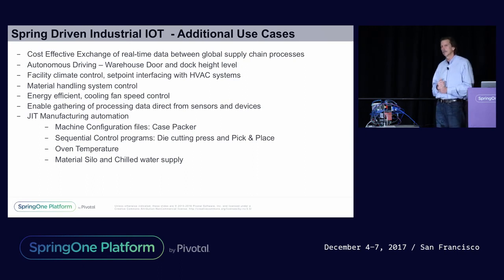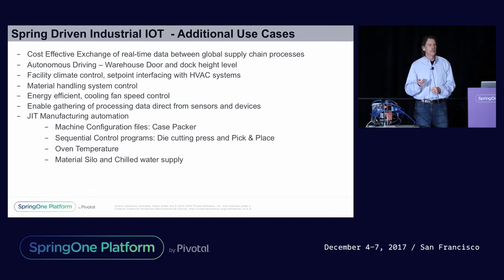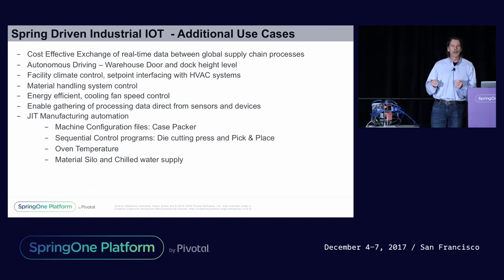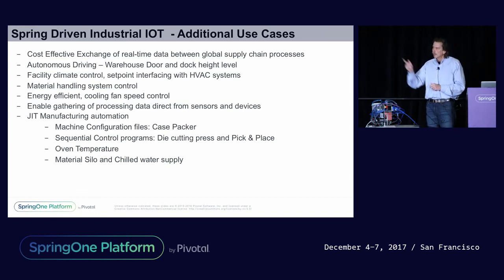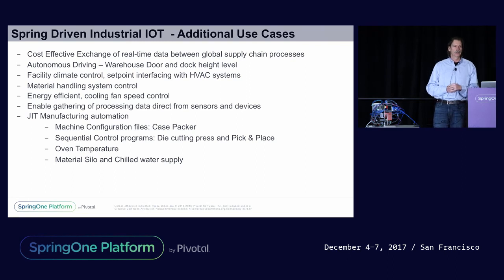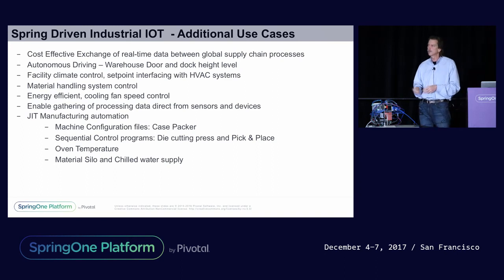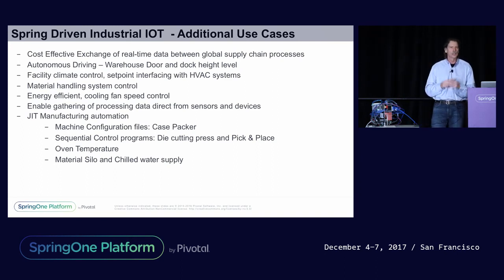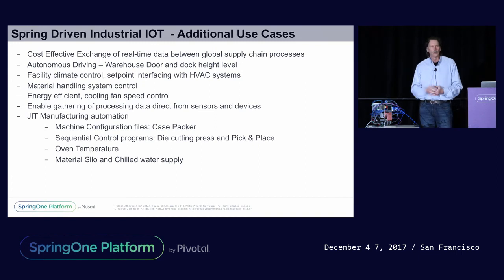Most companies that use chillers run those chillers at night when they have the least power usage to balance out their power usage, and they store it in underground swimming pools. So basically, the enterprise knows what the next day's production levels are going to be, and it knows what the forecast temperatures are, so it can calculate the amount of chilled water it's going to need so that you don't overproduce chilled water.